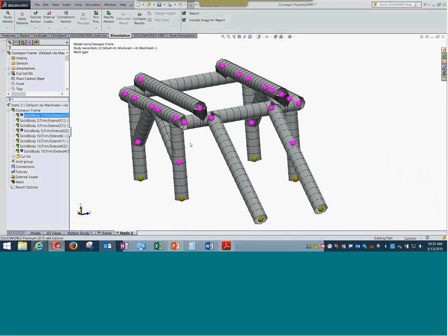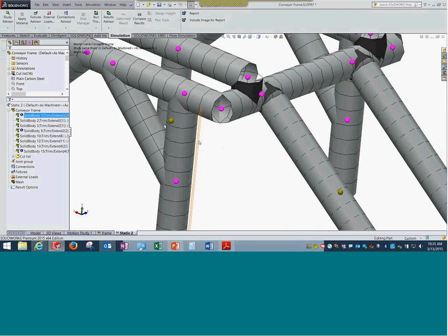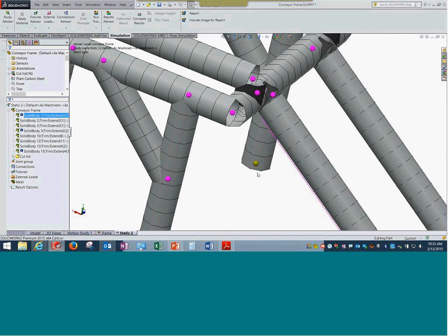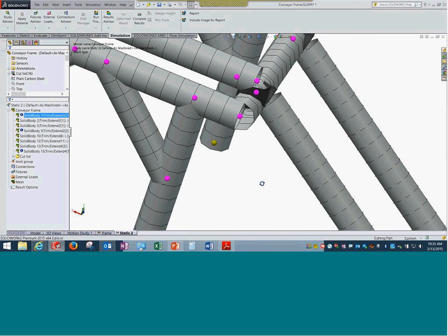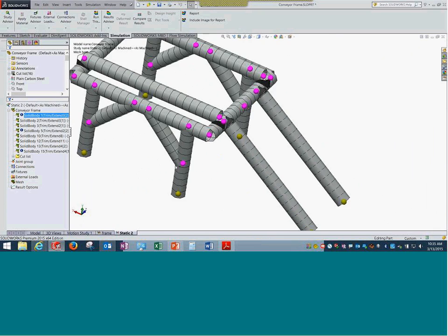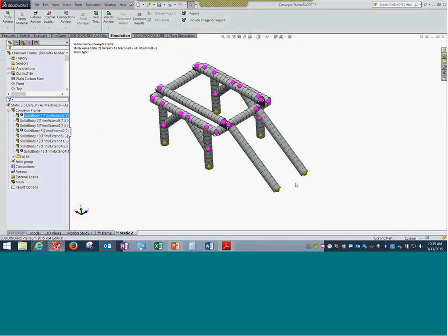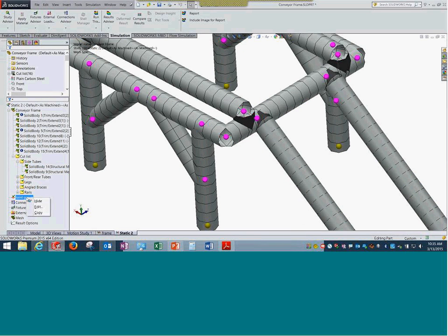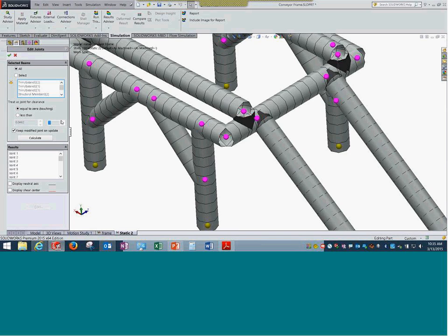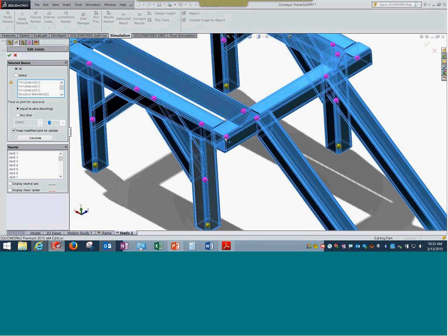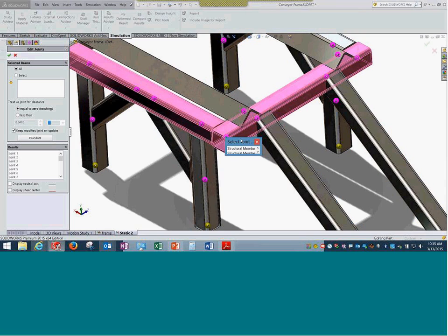Second, if there is a pink colored joint, this means that over there more than one beam is getting connected. There is also a gray colored thing which is more of an end joint. Those who are not aware, you can directly right mouse button click somewhere near the joint. Okay, I should be in the edit joint. Right click, edit, and somewhere in this option, I can right mouse click on that joint, and it shows us which are the different members.